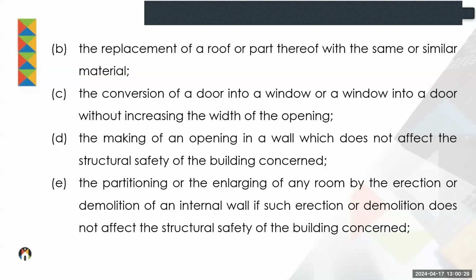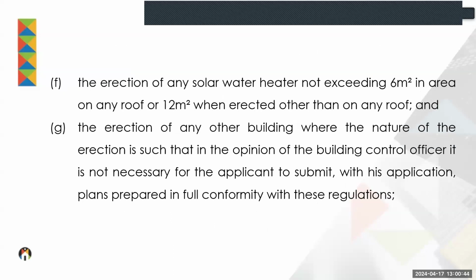The making of an opening in a wall which does not affect the structural safety of the building concerned, and the partitioning or the enlarging of any room by the erection or the demolition of an internal wall if such erection or demolition does not affect the structural safety of the building concerned. The erection of any solar water heater not exceeding 6 square meters in area, we all do those things these days, or 12 square meters when erected other than on a roof, and the erection of any other building where